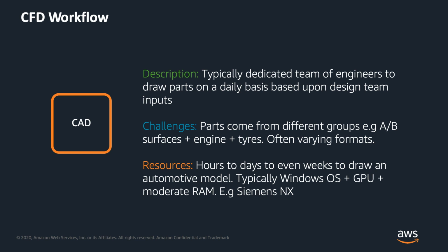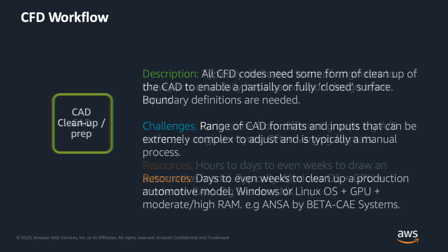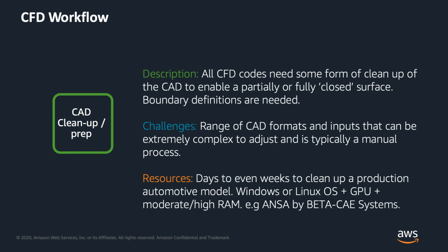Most people like to use things like Siemens NX. You need a GPU and moderate RAM. And of course, the thing that most CFD practitioners know very well is that all CFD codes need some form of cleanup of the CAD to enable a surface on which a mesh can then be generated.